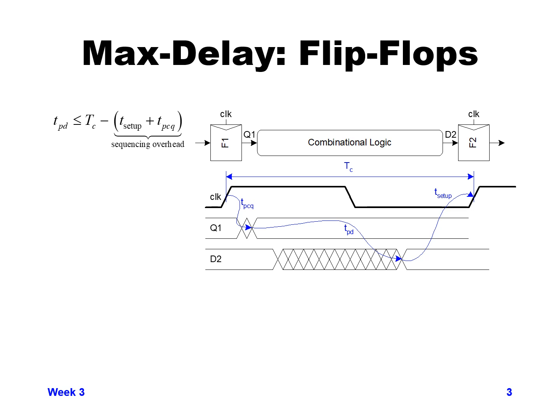If we try to put in combinational logic that takes more time than our calculated remaining propagation delay time, then we can't actually operate at that particular frequency of clock or that particular cycle time of clock. So you can see how the setup time and propagation delay time of the flops can help determine what frequency you can run at for your chip overall.